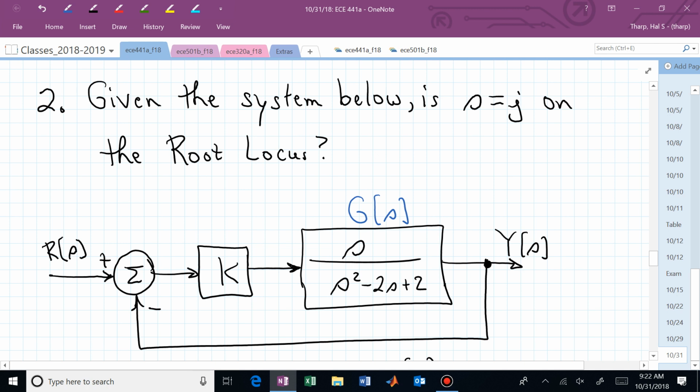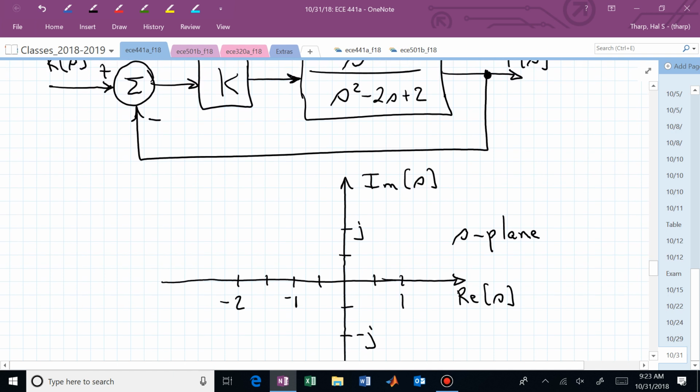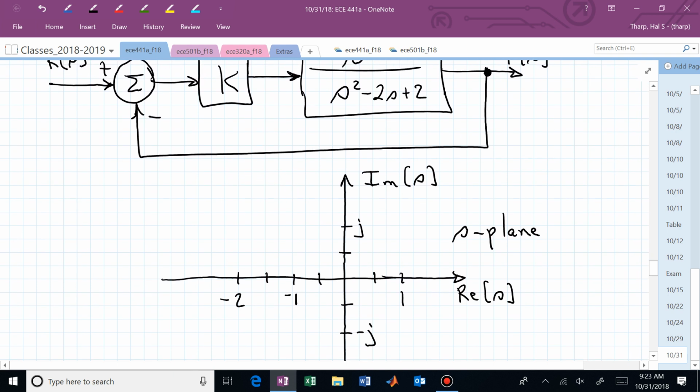In this case, what's our transfer function? That's G of s. And what's the picture look like? Here's our s-plane. And now these tick marks are every half. I tried to make this a little bit bigger. So 2 tick marks gives us a unit spacing. But do we have any finite zeros in this case? For this G of s, we had 1 zero right at the origin.